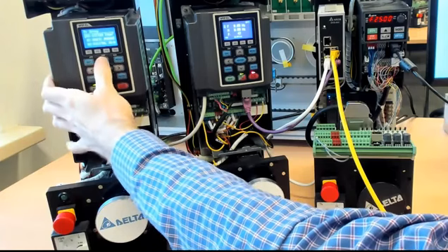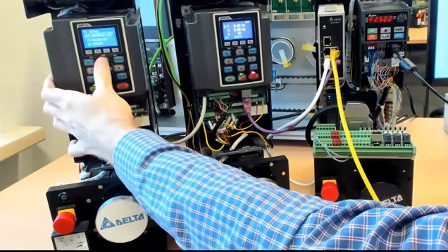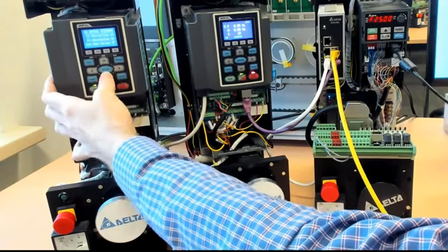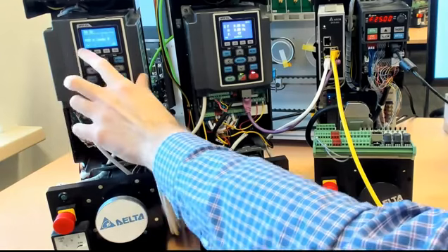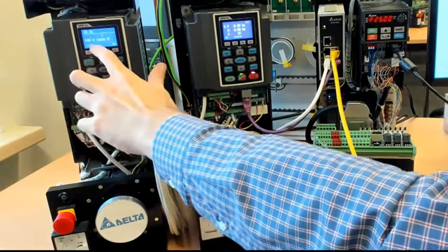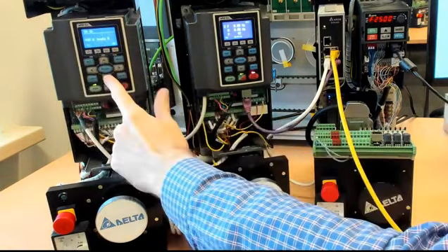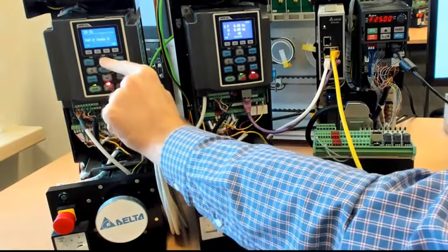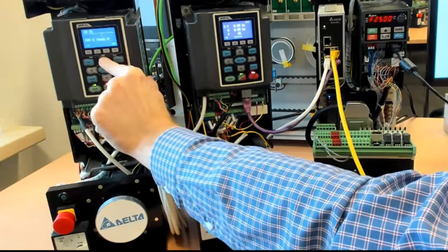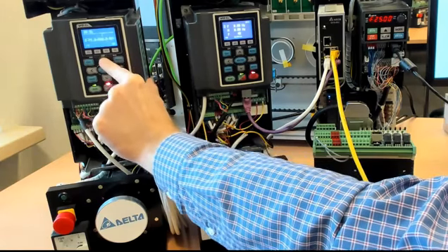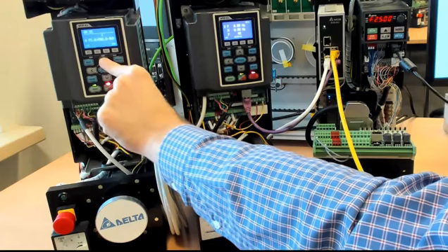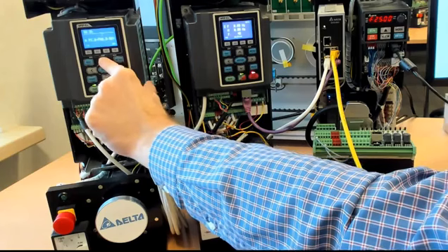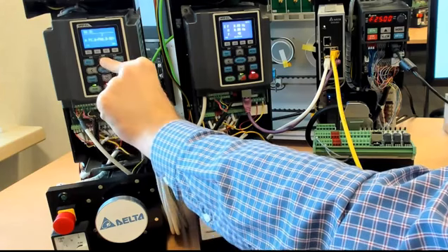Firstly, you need to set parameter 1016. You need to tell the drive that the reference pulses are A and B type. You can have different types of pulses. You can also have B type leads, or just A and forward or B and forward type of pulses, so pulse and direction.